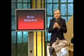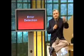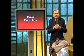At the receiver end, your friend would be counting the number of ones. If they are even, then the message is correct. If they are not even, the message is incorrect. So we either use the odd parity method or the even parity method to detect 1-bit errors. Let us have a look at an example which explains this parity bit method of detecting errors.